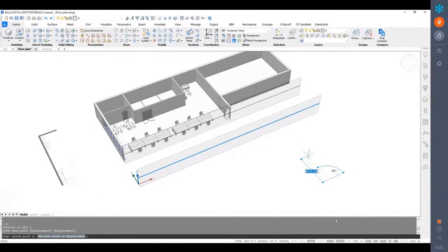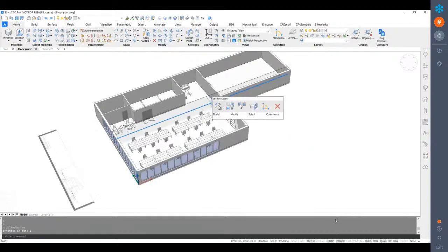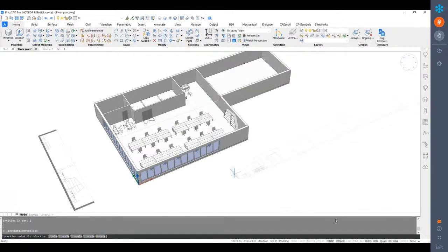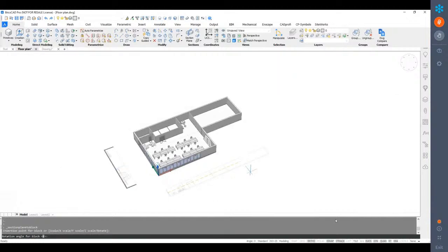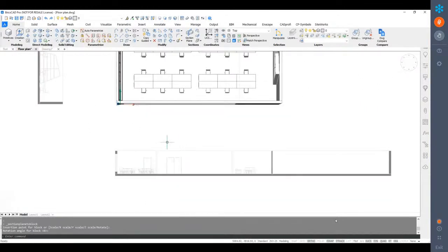So maybe just to see this view, and I can easily need to close it so it doesn't get cut. So let me just extract that part here. So you can find it here. And it's so easy to just have our elevation or interior elevation. And you can immediately go into your layout space, your sheets, and do your documentation on your sheets.